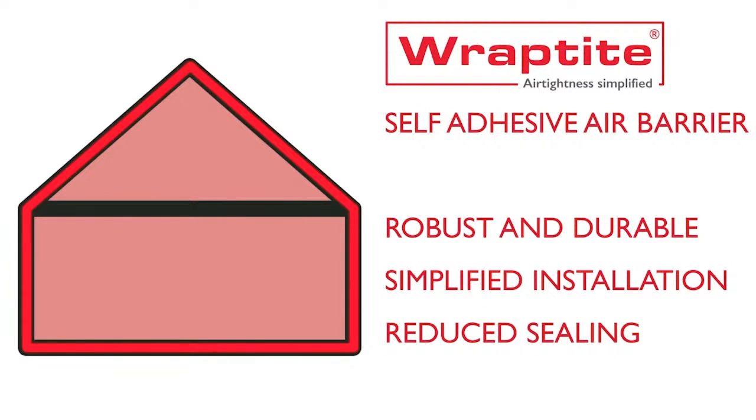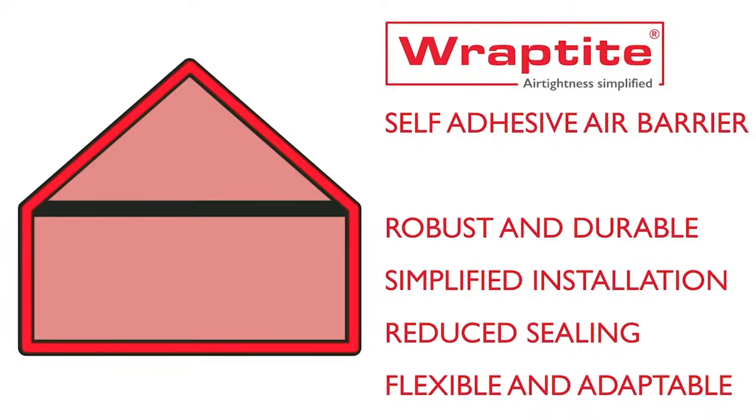In buildings constructed using cross-laminated timber or structural insulated panels, the Wraptite can be used to seal the panels immediately after erection, providing weather protection and a wind and watertight envelope to begin internal works. It can then have additional insulation fitted externally as necessary, providing a flexible and adaptable construction method that can accommodate a variety of thermal performance targets.